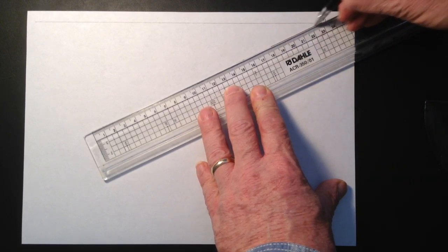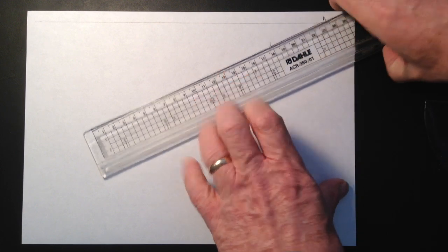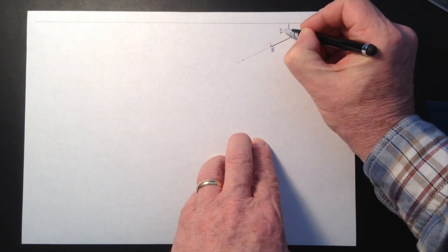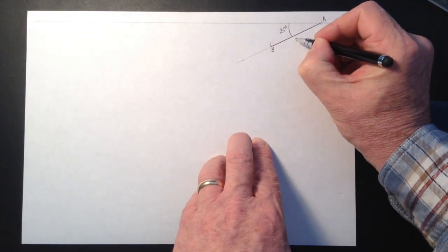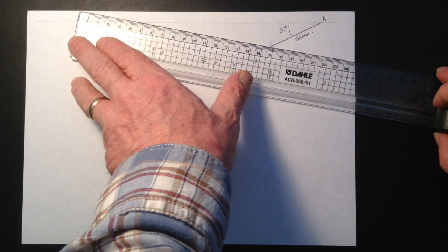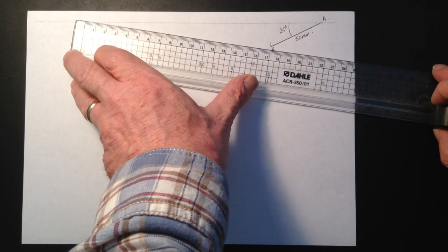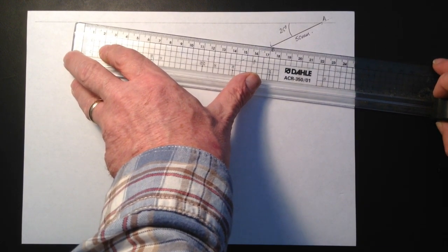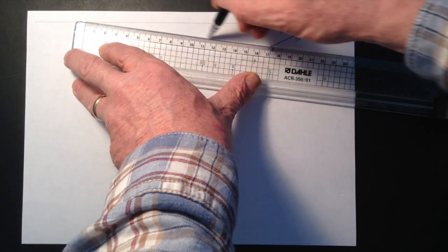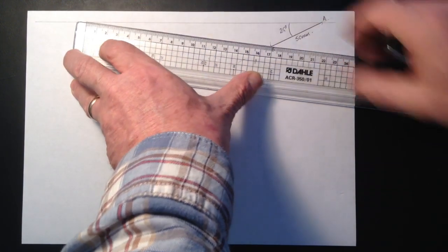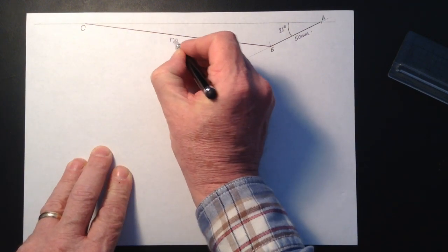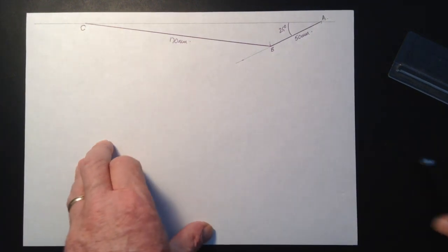And then I'm ready to draw in my first crank. So this gives me point A and point B. So get it labelled up, 25 degrees, 50 millimeters. Okay, now let's get our second line in, which is 170 millimeters up to the piston. So we can now label C. So that's completed our space diagram. This is our base geometry that gives us the directions for our vectors.